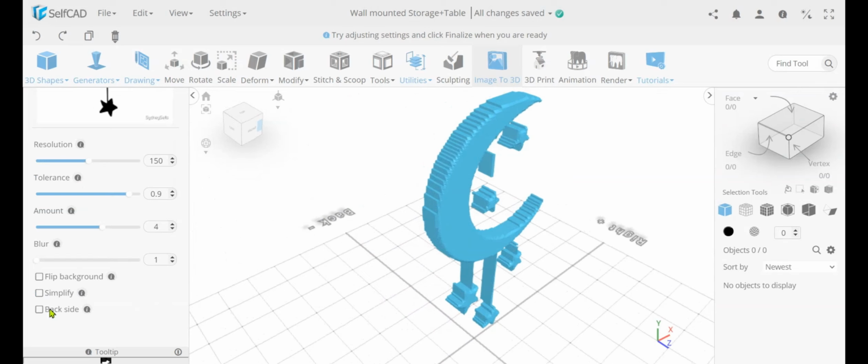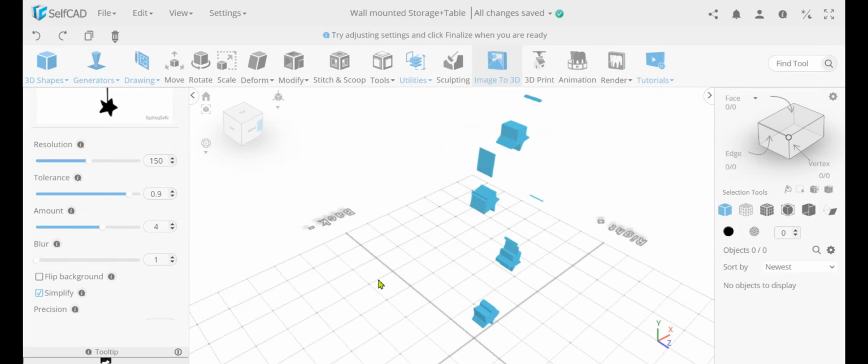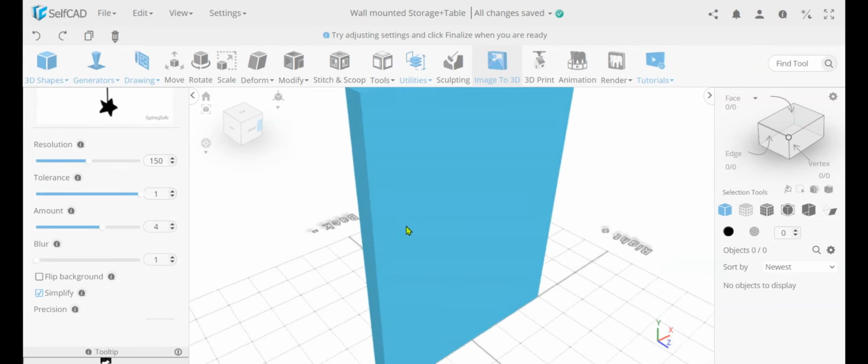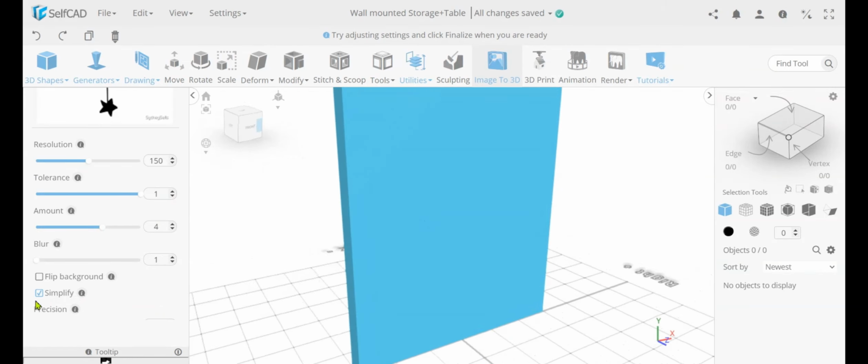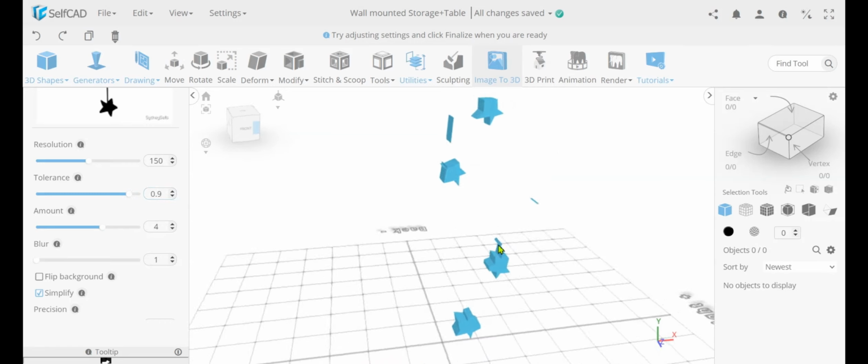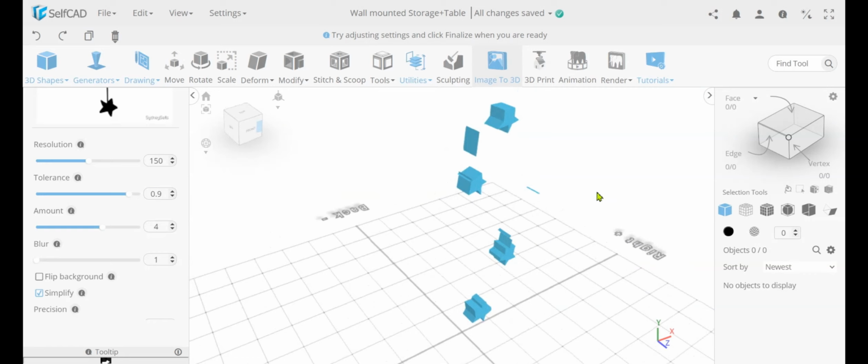The simple answer is to use Simplify. Simplify is designed exactly for this, but it's not as simple. So you see, if I increase the tolerance, Simplify will simplify everything. What this does basically is post-processing, and this is actually the most process-intensive thing you have here, because this is post-processing. We first take the image, and then Simplify will try to find edges and redo and simplify them. And if I have a tolerance of something like this, it simplifies the flat side also, it removes the entire image. So I can start playing with the tolerance.